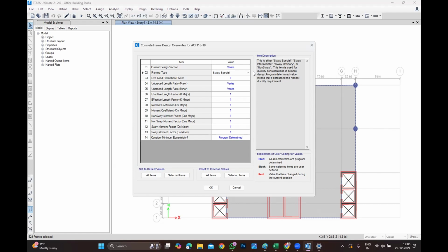Look at the project which is very close to Muktam, on the right side, you might have seen there is a 24-floor tower going up. We left out the podium because our scope is only for 6 floors. What happened? From the 4th floor onwards, till the 17th floor, all the columns stop. In that case, a transfer beam is not going to be helpful.